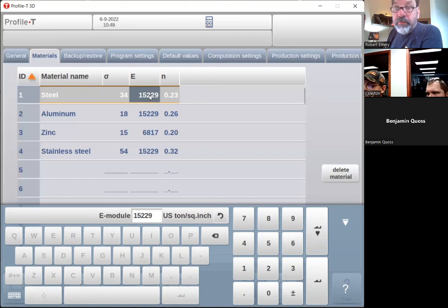I don't know the correct numbers for the material you're buying, but I would hope the person you're buying it from does. There should be a data sheet. You should be able to find tensile pretty easily. E-modulus is harder because it's a formula, but there should be 2 of the parameters on the data sheet, and there's some formula that calculates it.